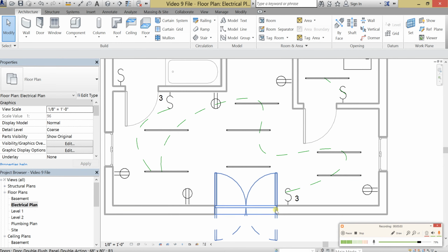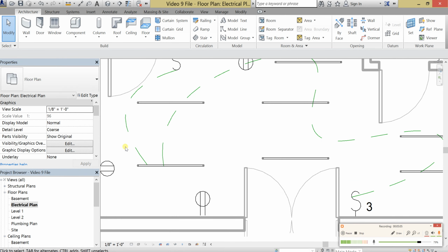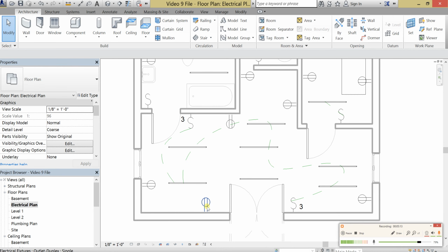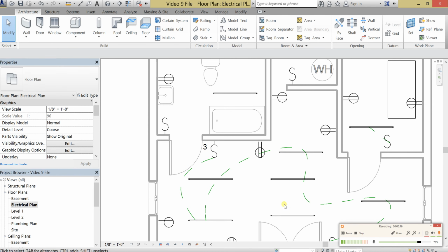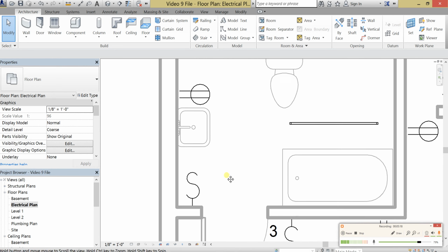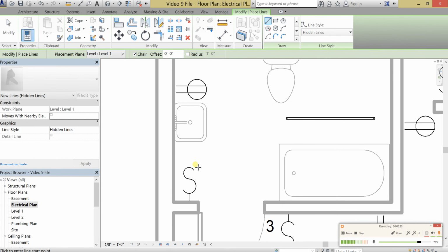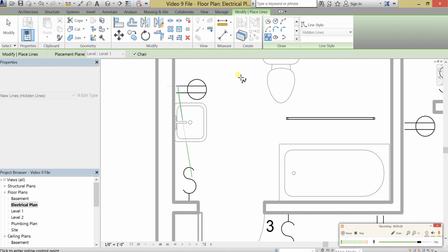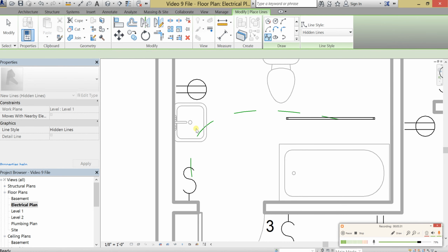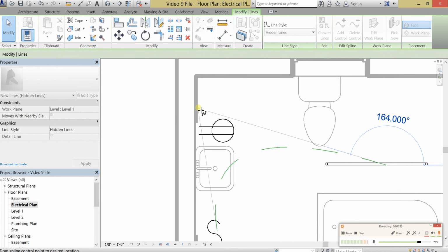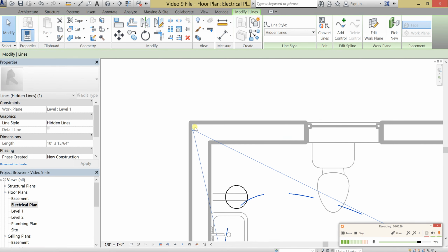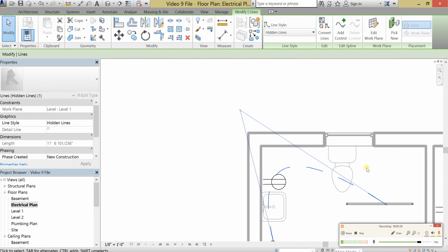We try to keep the wiring as simple as possible, and it is understood that there are multiple pathways in this cable so you can control it from either switch. Okay, all these lights are not controlled via the light switch, but if they were, let's say for the bathroom, this was only powered when this switch was turned on, it's the same deal. You're going to have the spline tool selected, and you're simply going to draw a pathway from your switch to the lights and vice versa. Try to keep everything inside the building and contained such that it makes sense.